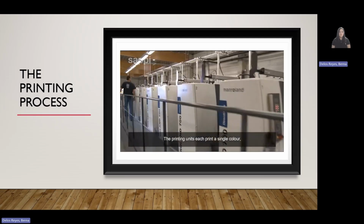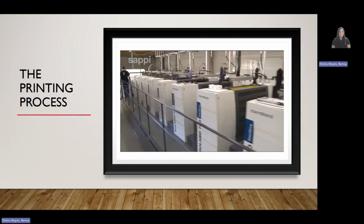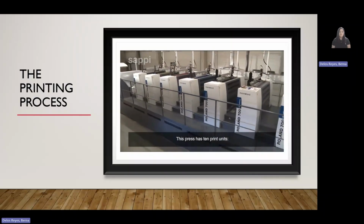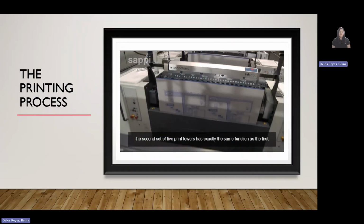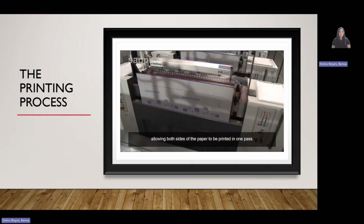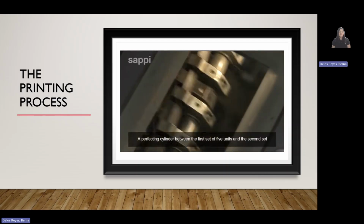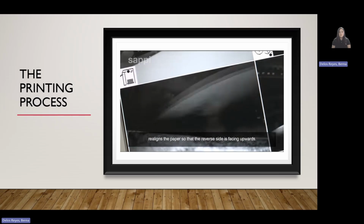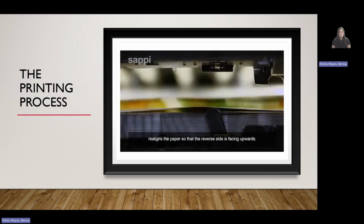The printing units each print a single color on only one side of the paper. This press has 10 print units. The second set of 5 print towers has exactly the same function as the first, allowing both sides of the paper to be printed in one pass. A perfecting cylinder between the first set of 5 units and the second set realigns the paper so that the reverse side is facing upwards.